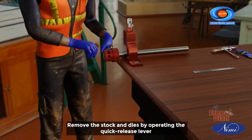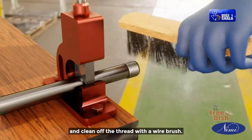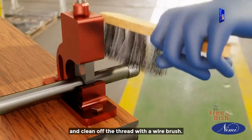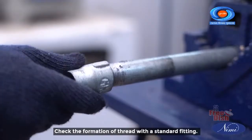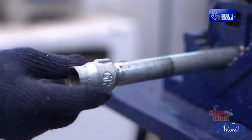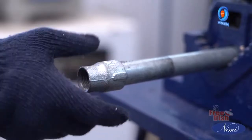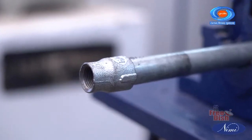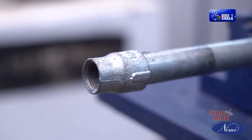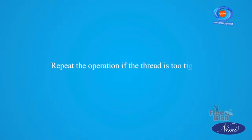Remove the stock and dies by operating the quick release lever and clean off the thread with a wire brush. Check the formation of thread with a standard fitting. Repeat the operation if the thread is too tight by adjusting the dies.